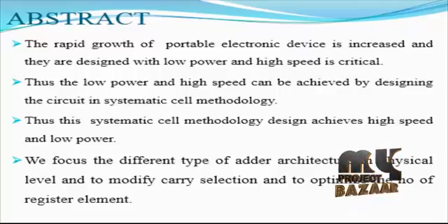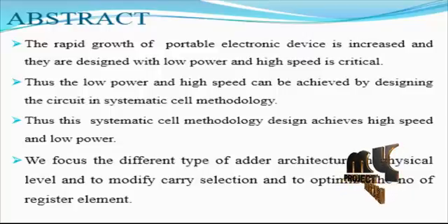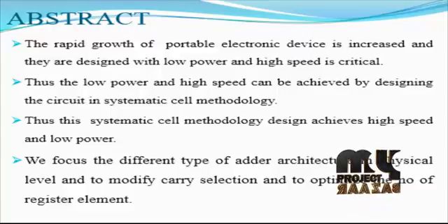At first, priority is deliberately given to general design goals in the basic structure of the circuit. This structure is generated systematically by employing the binary addition diagram. After that, concerning high flexibility in the design targets, SCDM aims at specific ones in the remaining 3 steps, which are wise selection of basic cells and aimed mechanisms, as well as transistor sizing. In the end, the outputs perform well with supply voltage scaling and their critical path contains only 2 transistors.